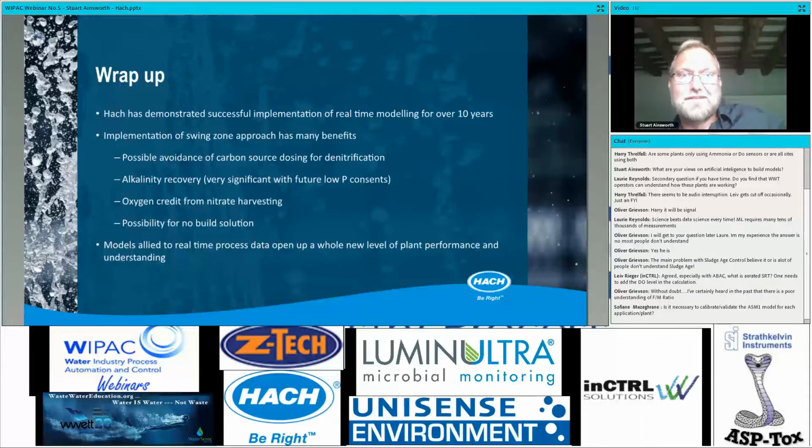And because we've got that validated feedback signal, that gives you another piece of information, because you can tell how much the feedback element is weighting the DO set points. Just by understanding how much influence that feedback controller has, that gives you a level of calibration that is very difficult without both measurements.